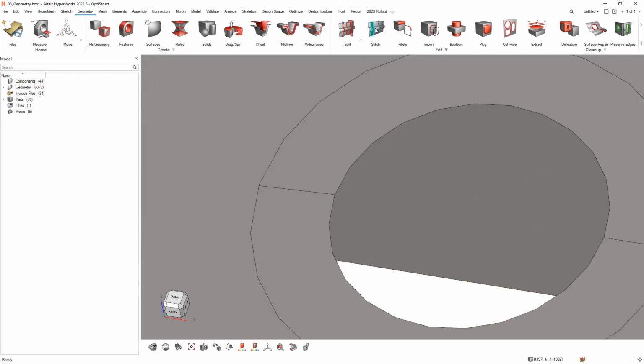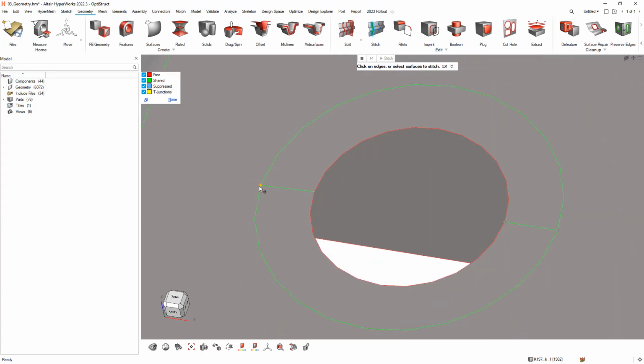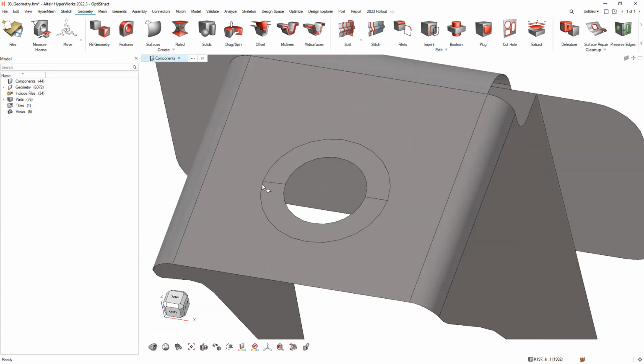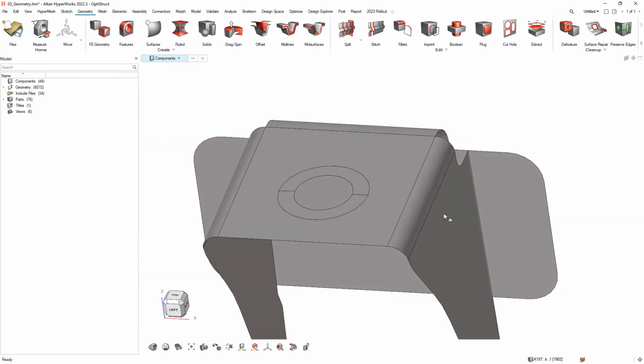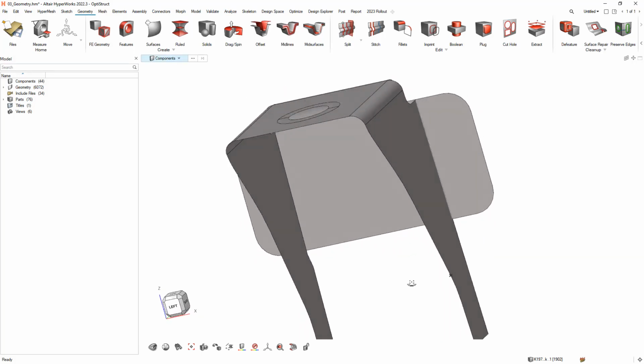The stitch tool is also available to edit topology directly, again using drag and drop to simply take points and lines and stitch them to the appropriate geometry. So I can remove those adjacent points. So in a couple of minutes, we can defeature and split the geometry.